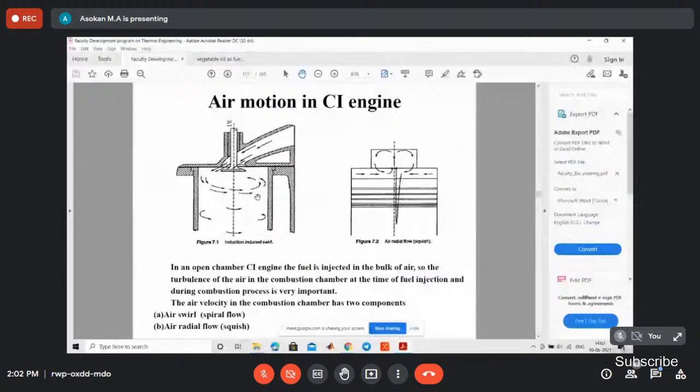So already it is a swirling motion. Then the compression moves the air from the bottom side toward the center. Then this air is compressed. So because of the shape of the combustion chamber, right? Here this compressed air rotates perpendicular to the axis of the cylinder. Squeeze motion. So swirling motion occurs when the piston moves in a downward direction. There is a suction swirl, and the squeeze motion occurs during the compression time. Right? This increases the combustion rate. Right? It decreases the ignition timing.